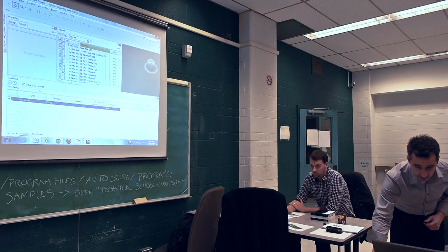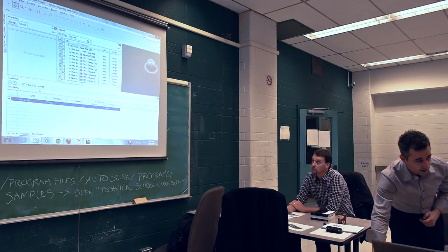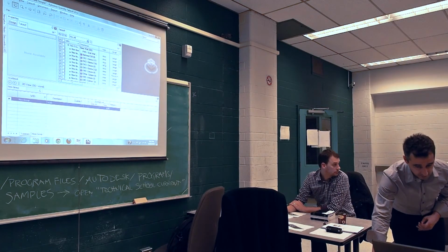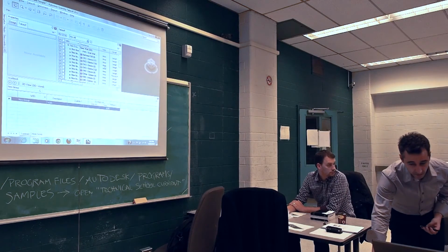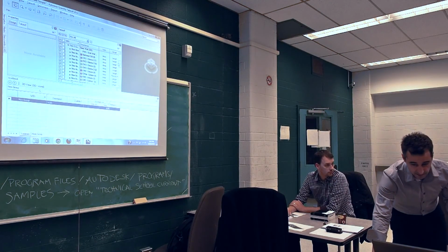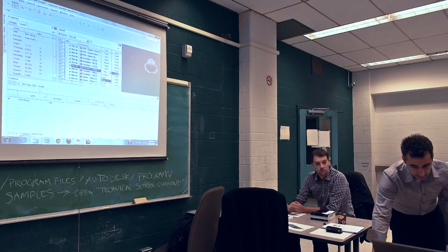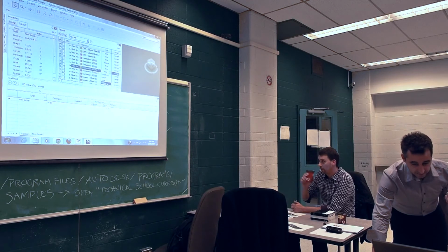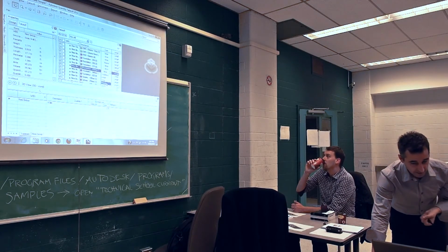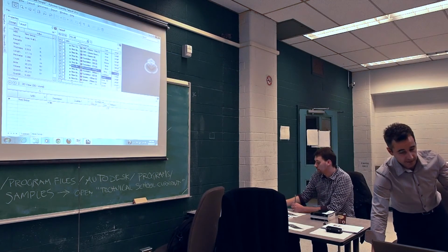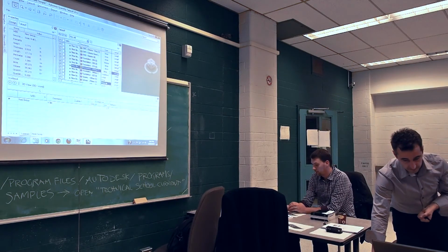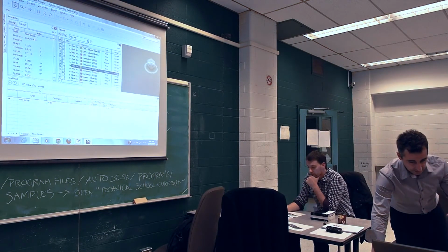And this is what I was talking about. In here, you can actually define the type of takeoff that you want to do. So if this is an exterior wall and area is what you are interested in, that's fine. If it's a foundation and it's concrete, then maybe this one is volume. If it's a door, then count is going to be it. If it's a railing, linear footage, right? So I'm changing this as needed.